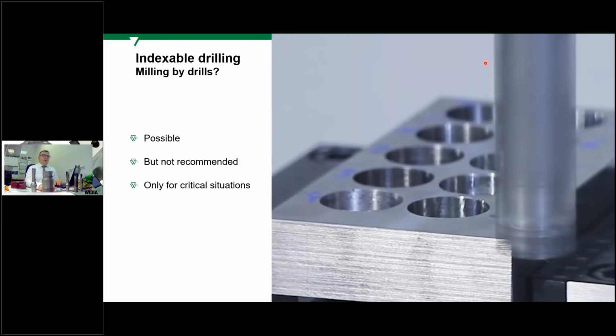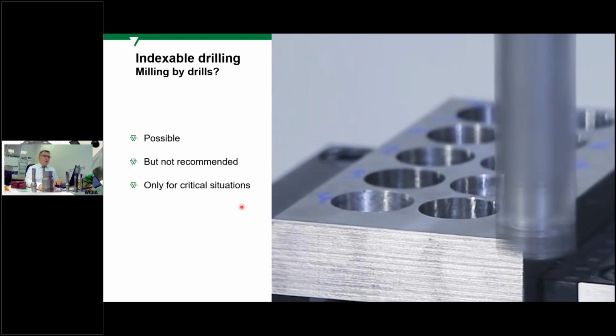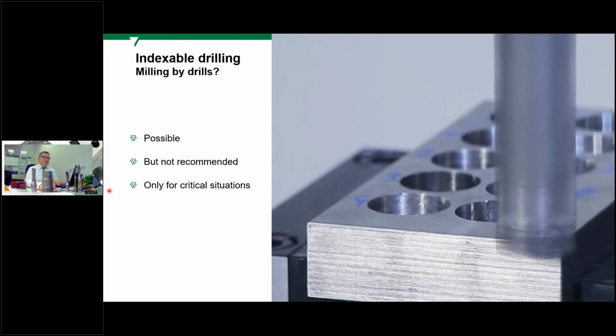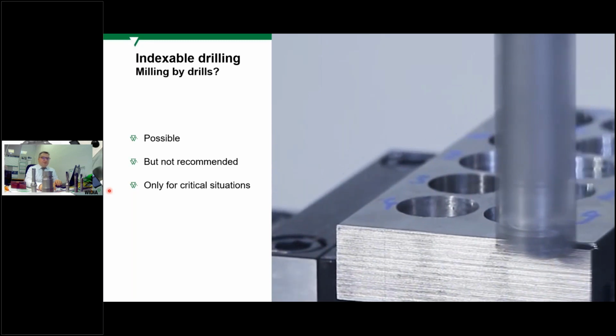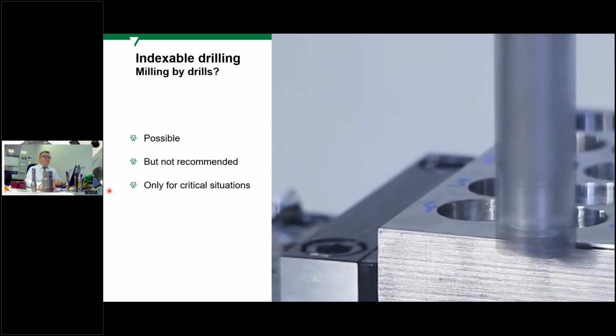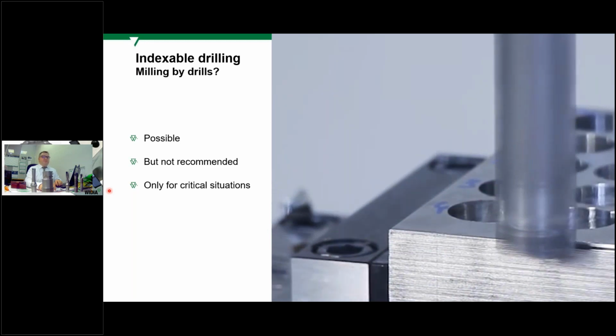Also, you can use the drill for milling, but it's not recommended, only in critical situations, if you don't have end mills or other milling cutters at all.